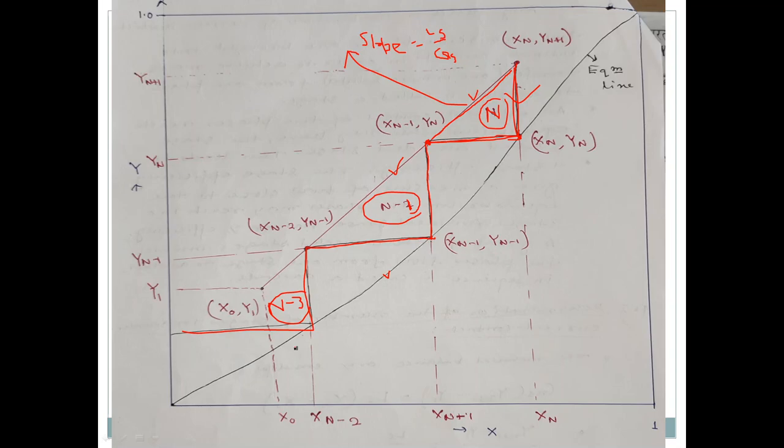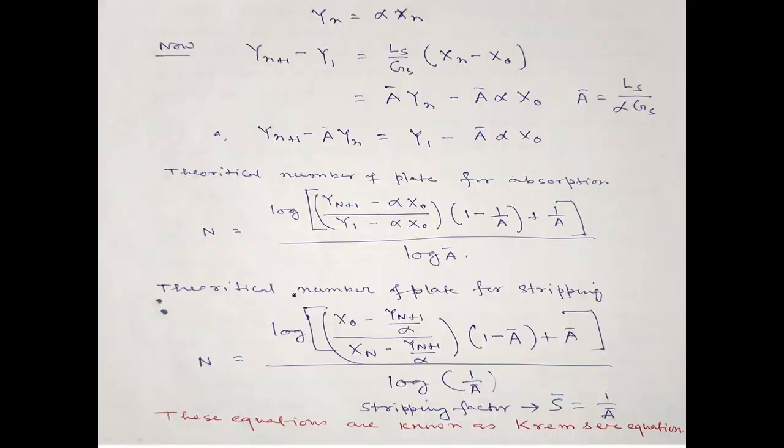Okay. So here, this is the one way we have done this graphically. For this we have the equilibrium curve. Then from the material balance we get the operating curve, and I will make the triangles. Each triangle corresponds to one stage or tray. For my system, these two points will be known to me according to the problem. So I can calculate how many stages are required, and according to the tray spacing I can easily tell what will be the height of that. Also, the number of stages can be calculated.